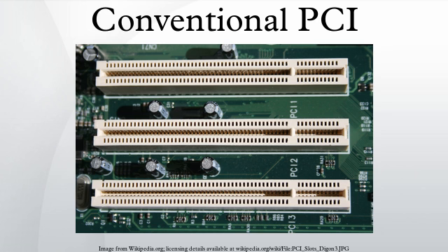Each device can request up to 6 areas of memory space or I/O port space via its configuration space registers. In a typical system, the firmware queries all PCI buses at startup time to find out what devices are present and what system resources each needs. It then allocates the resources and tells each device what its allocation is. The PCI configuration space also contains a small amount of device type information, which helps an operating system choose device drivers for it, or at least to have a dialogue with the user about the system configuration.